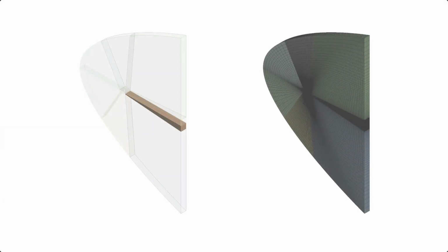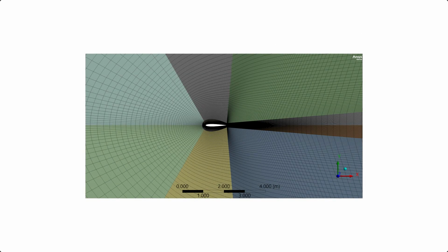So until now, we designed the basic geometry of our model in Design Modeler software, and then via Ansys Meshing, we could generate a structured grid using 440,000 hexagonal cells in order to divide our domain.